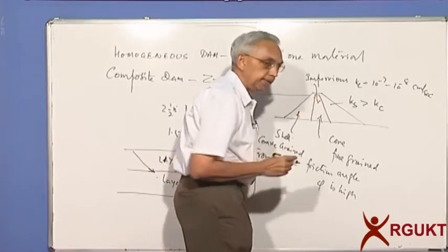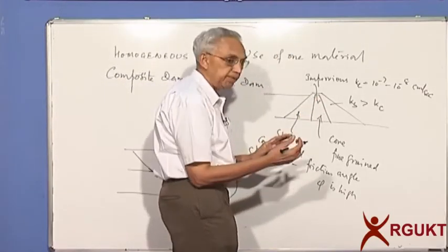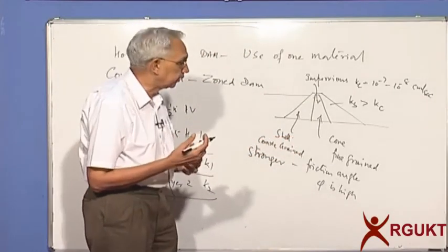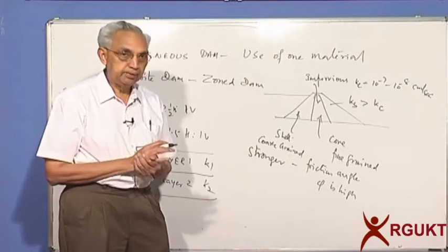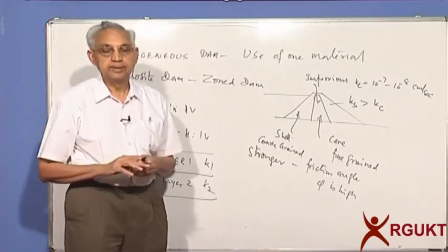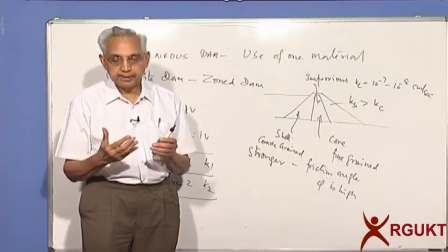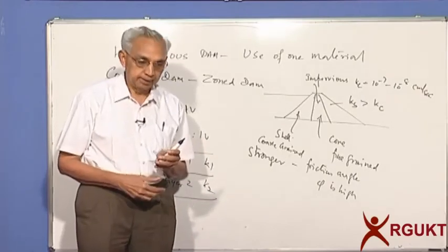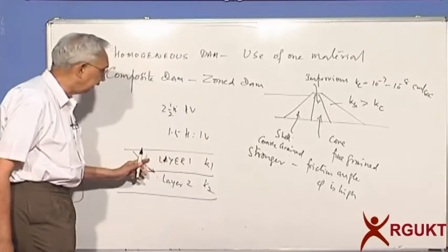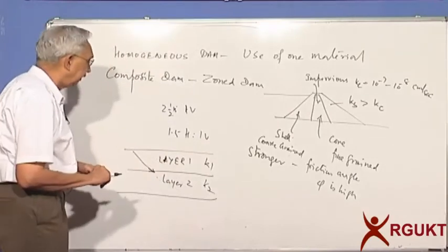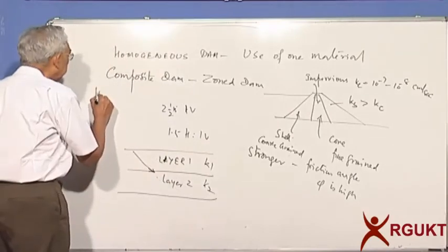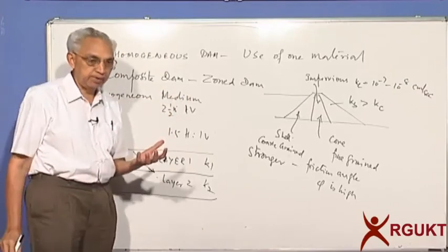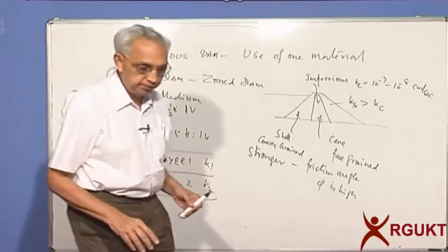You will find that when you have two different materials, what happens to the flow net? That's a very important practical aspect that you'll have to consider, because the permeabilities are not the same, they keep varying from one point to the other. And if that happens, it is a layered profile, or you can say a non-homogeneous medium. What will happen to the flow path or flow net? It's a very simple modification.